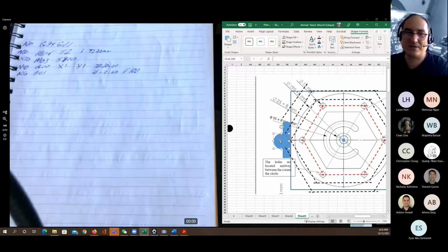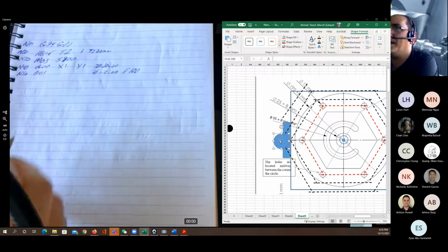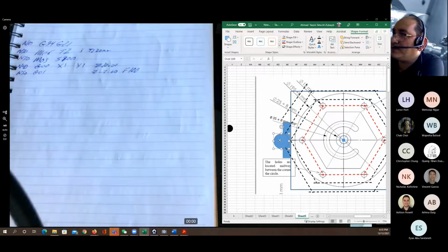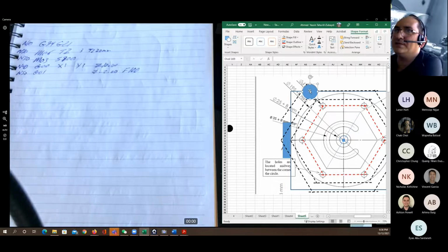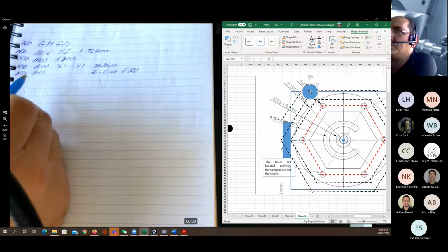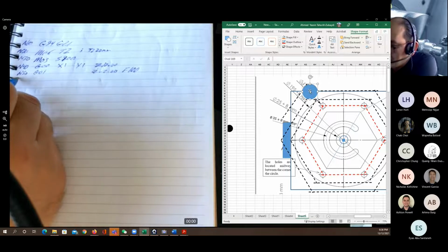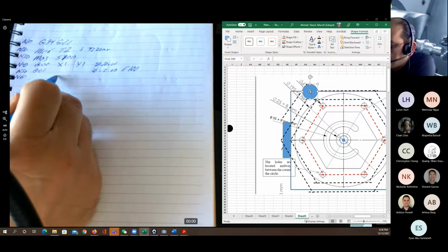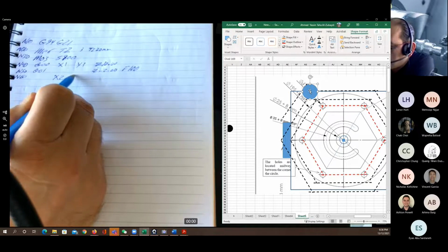As I told you, you can find the numbers because I don't want to spend time calculating that now. Maybe I have an old video I can share with you that will help you on how to do it. Once again, we are going to move the cutting tool center from this point to point number 2. So it's going to be G01, and G01 is not going to be changed. We are going to write down here X2 and Y2.